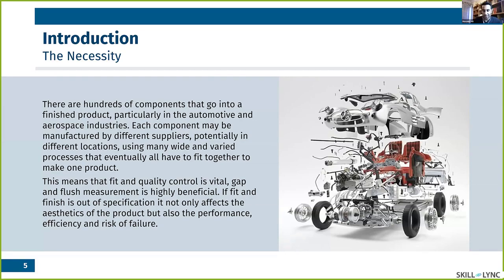But since it's going to be opened and closed thousands of times, it needs to be considered in such a way that after 2 years of using it, we wouldn't be faced with a bulge on the exterior of the car. So we need a flushness in the reverse direction, into the center point of the car.